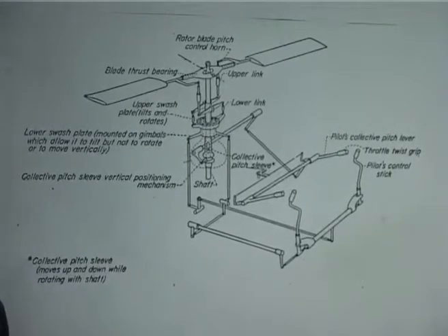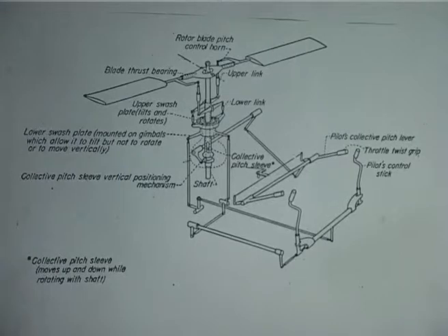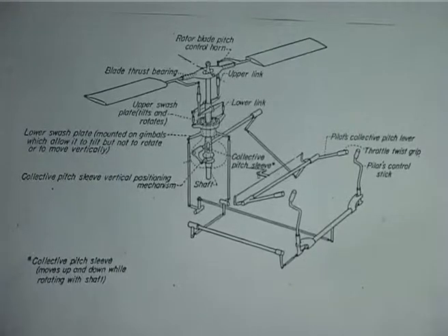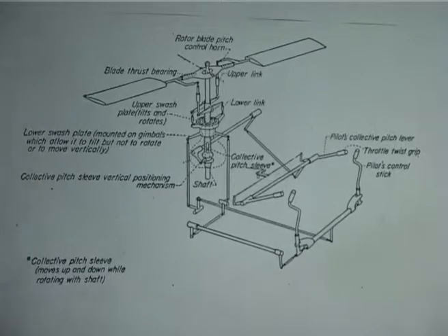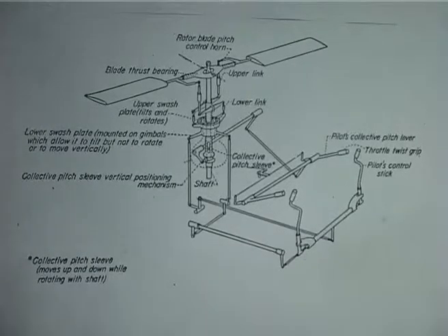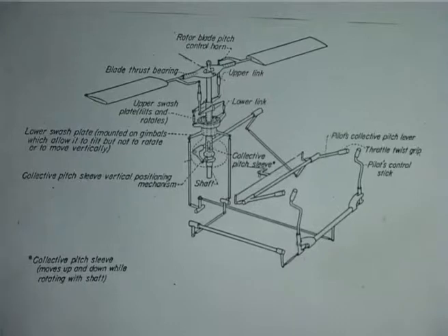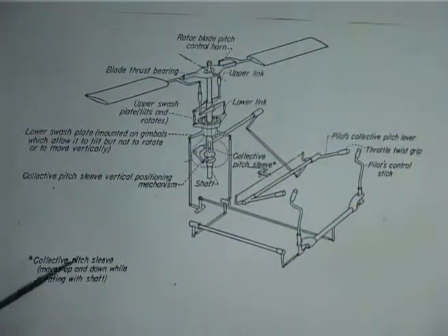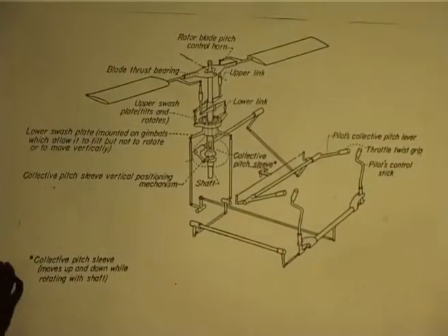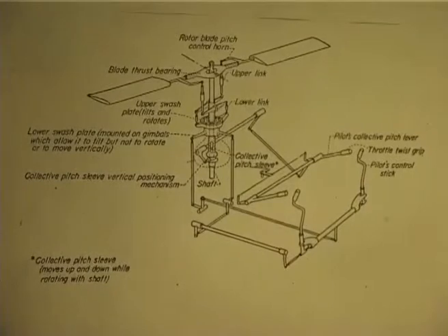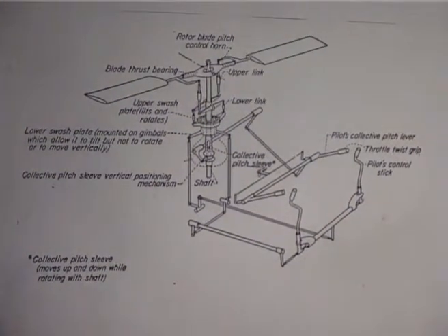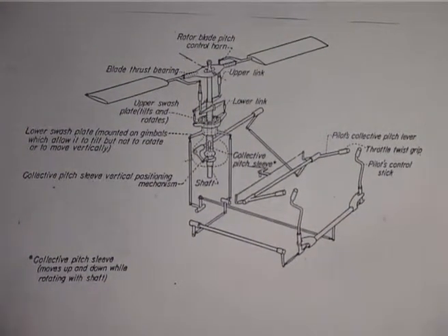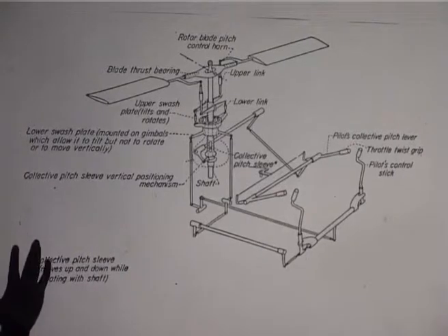It is only within a zone, because you will have a meter that tells you the rotor RPM and the engine RPM. Please understand, in helicopters, whatever we are going to develop from now on, in terms of equations of motion or thrust, power, anything, rotor RPM is a fixed quantity. It is not a variable quantity. That is in helicopters.